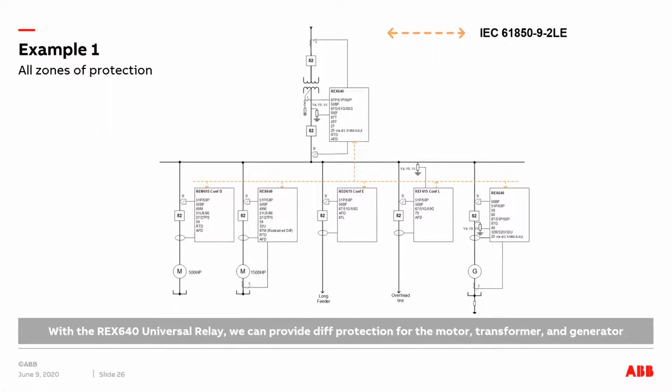And in addition, we now have the ability to share the voltage between the devices, which means the bus voltage can be shared between all the devices. And if there is a line voltage to be checked for synchronizing purposes, that can be checked as well. For example, here in the generator protection, you have a line PT or line voltage sensor, and then the bus voltage sensor coming from the sample value, and it checks the synchronizing condition before you can close this breaker and bring the generator onto the bus.